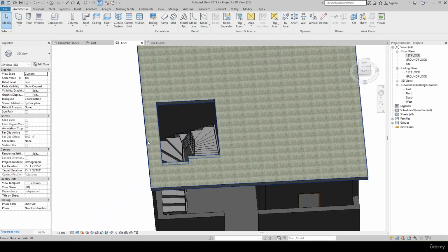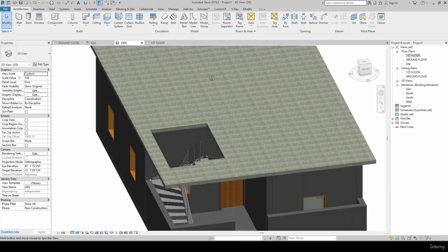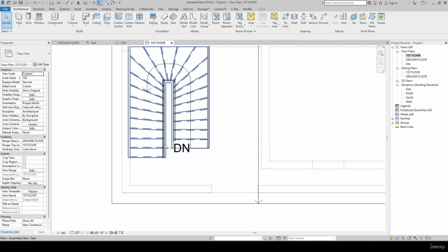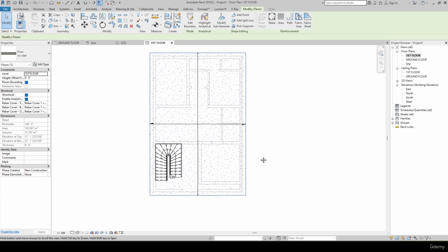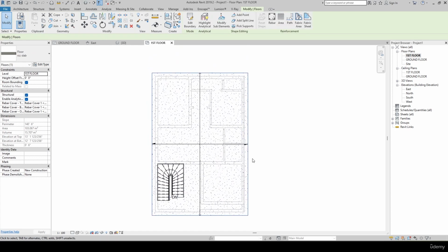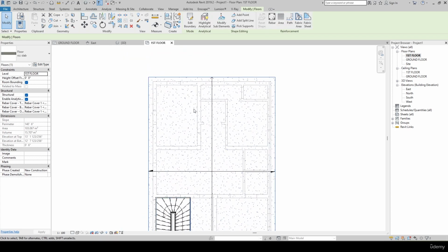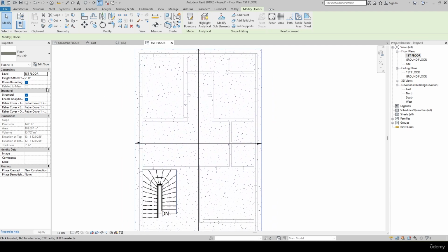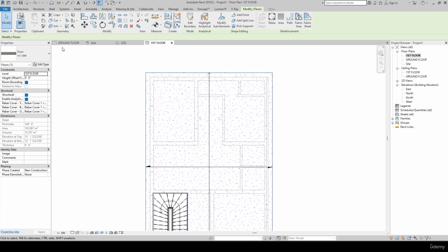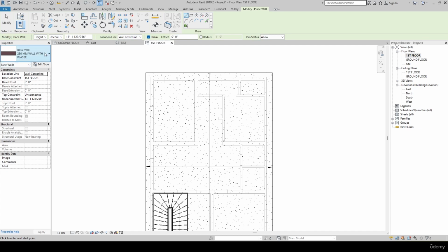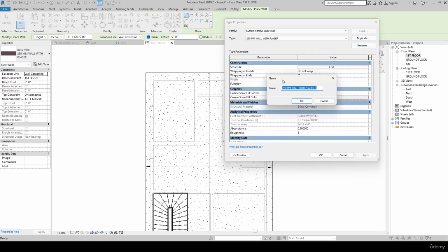You can just add the hand railing surrounding here and you can just close once again here. So again on the first floor I'll go somewhere here. I'll simply add the parapet wall and then I'll close the railing. So I'll go to here, I'll add the parapet. So in order to add the parapet and above here, WA, okay, I will take 230 as the wall thickness. I'll make this a duplicate, parapet wall. Okay, parapet wall, thickness is fine. I'll keep this as unconnected.